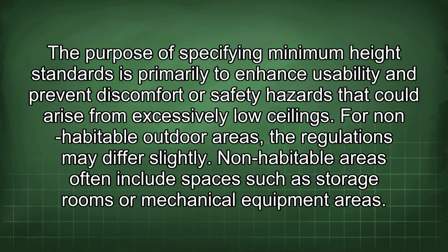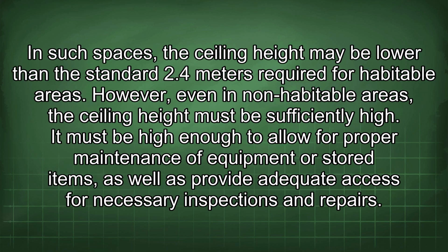The purpose of specifying minimum height standards is primarily to enhance usability and prevent discomfort or safety hazards that could arise from excessively low ceilings. For non-habitable outdoor areas, the regulations may differ slightly. Non-habitable areas often include spaces such as storage rooms or mechanical equipment areas. In such spaces, the ceiling height may be lower than the standard 2.4 meters required for habitable areas.